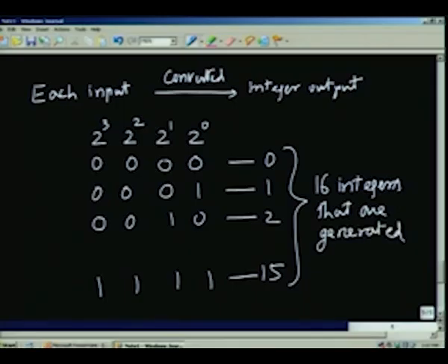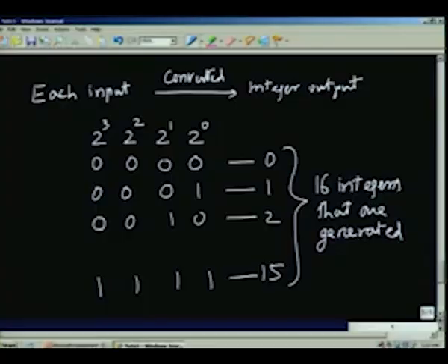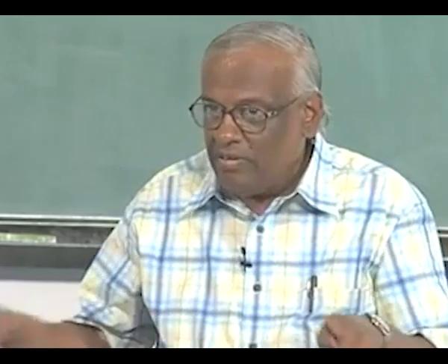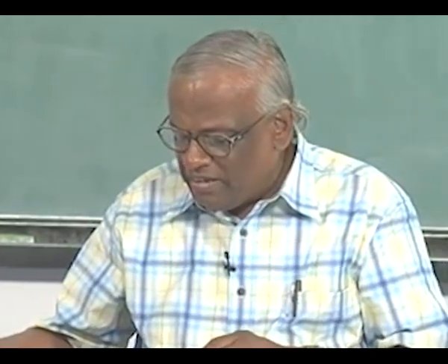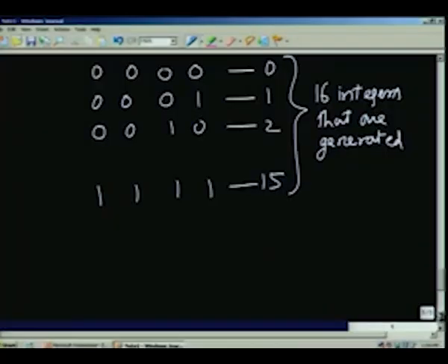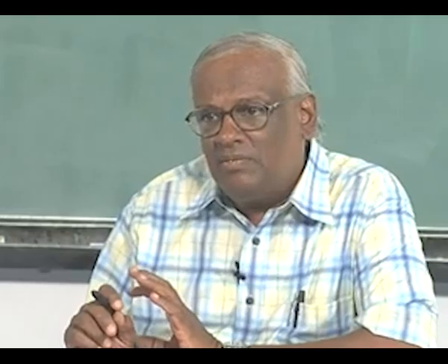That means, if the input 1 volt corresponds to the last number 1111 all high, and 0 corresponds to 0000, the 1, 2, 3 etc. correspond to the fractions. So, it is like dividing the range by the number of such integers which I can represent. In the case of a 4 bit conversion, I only have 16 levels.